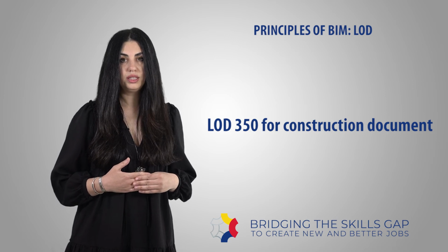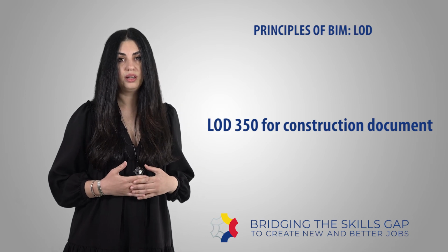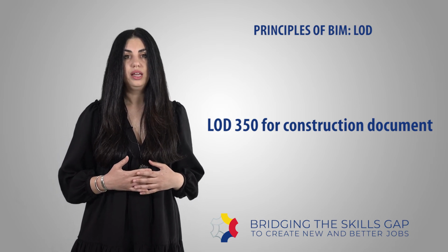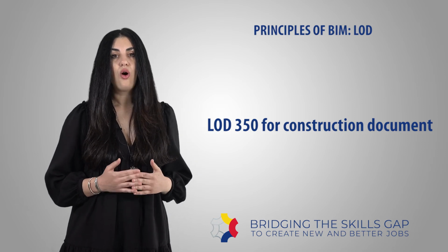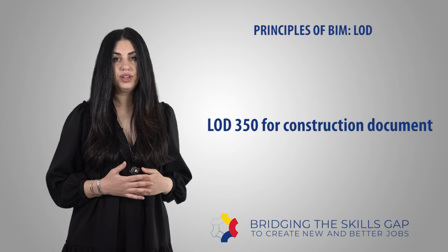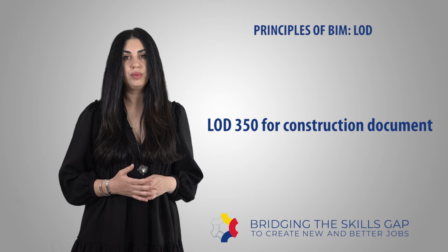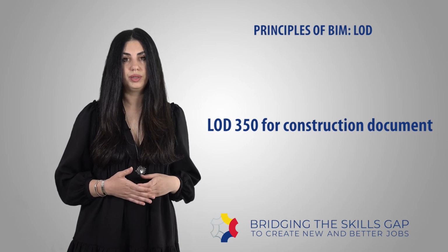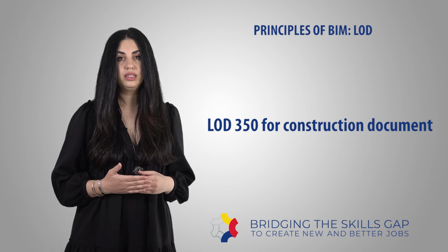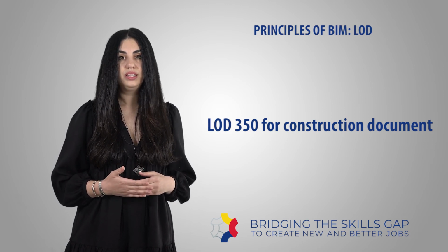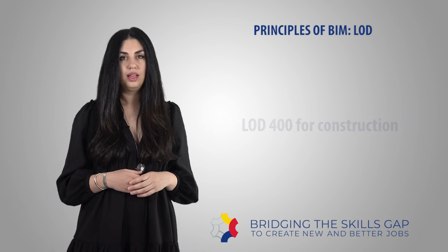The model element is graphically represented within the model as a specific element, object, or assembly in terms of quantity, size, shape, location, orientation, and interfaces with other building systems. Non-graphic information may also be attached to the model element. In our example, at this stage, the component needs to be developed with this base plate, exact shape, and location.